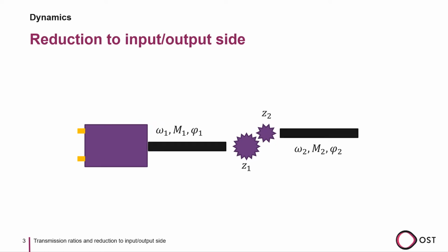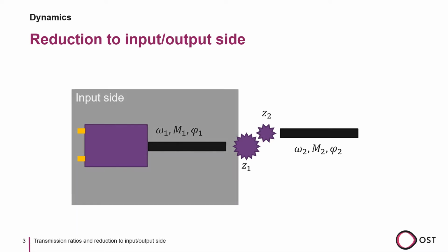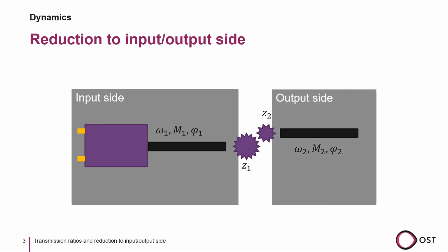We can use the transmission of a physical quantity in our control algorithms. That allows us to choose whether we want to express the controller in terms of the input side or output side of our system. If we take a motor with a gearbox as an example, we can express our controller in terms of the gearbox input or gearbox output. Both options are used and can be viable.